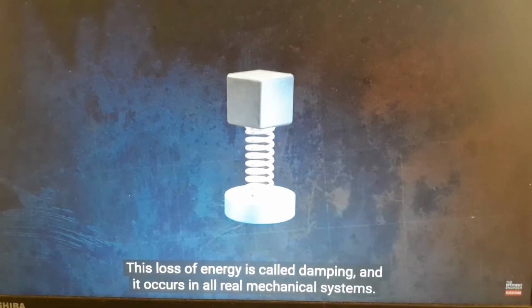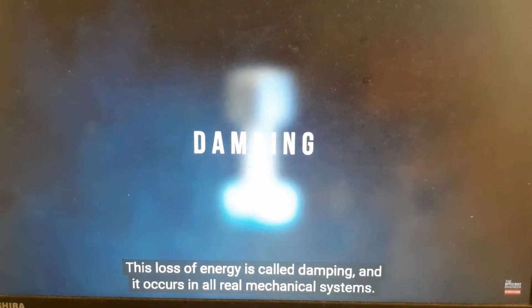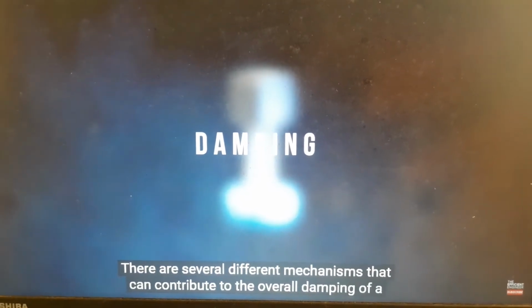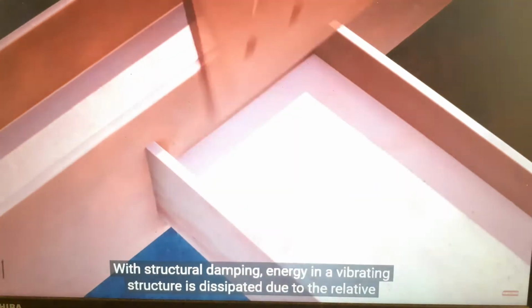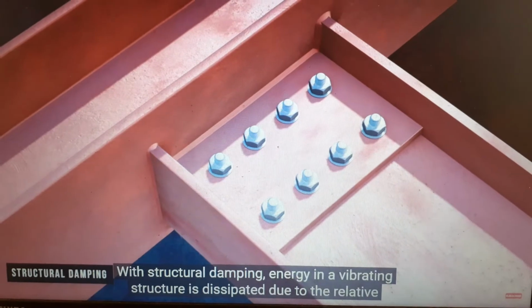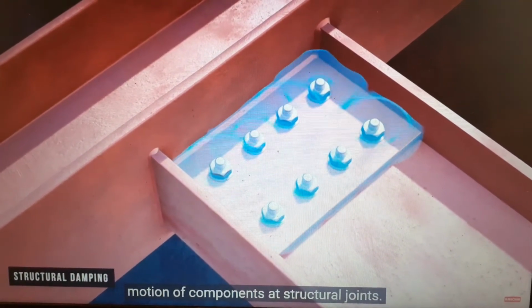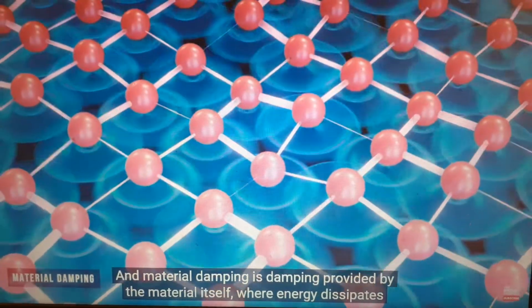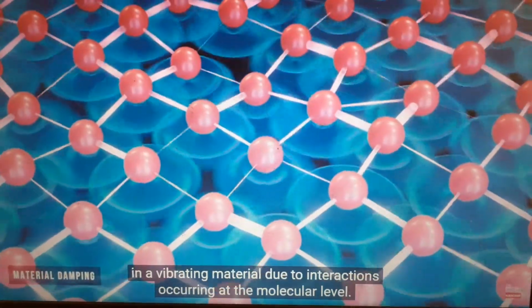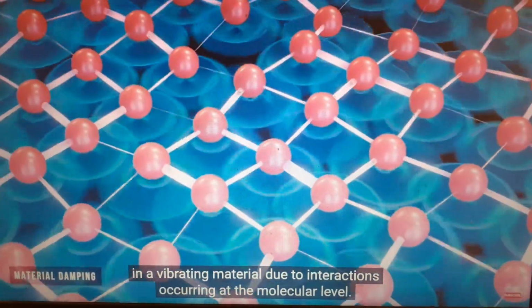This loss of energy is called damping, and it occurs in all real mechanical systems. There are several different mechanisms that can contribute to the overall damping of a system. With structural damping, energy in a vibrating structure is dissipated due to the relative motion of components at structural joints. And material damping is damping provided by the material itself, where energy dissipates in a vibrating material due to interactions occurring at the molecular level.